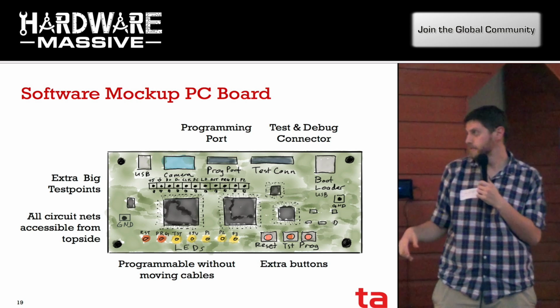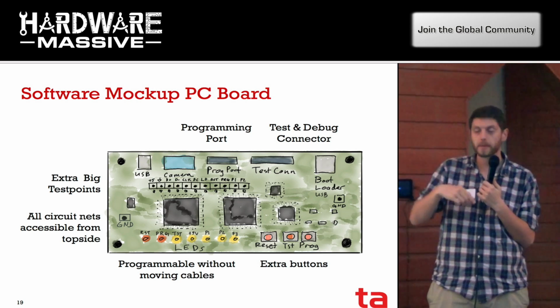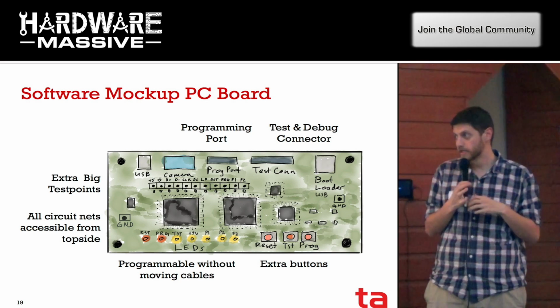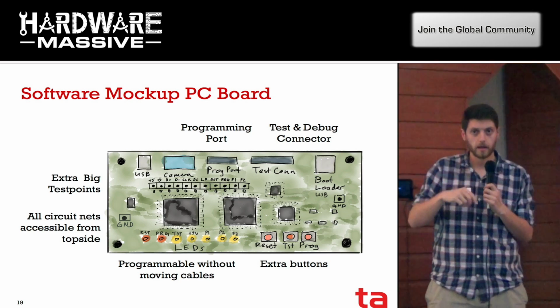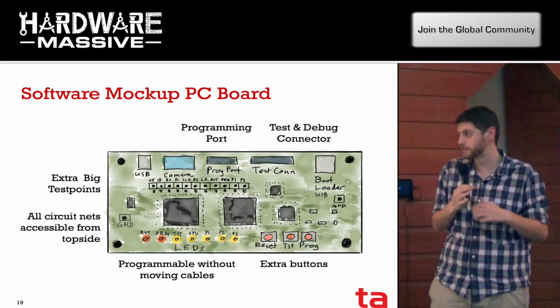A couple of other comments on it. It's nice to have the programming port broken out naturally and having that populated. Testing and debugging connectors, test points galore. If a software guy says, hey, it's not working, they'll hand it to you, and you can poke it and figure out why that's the case.